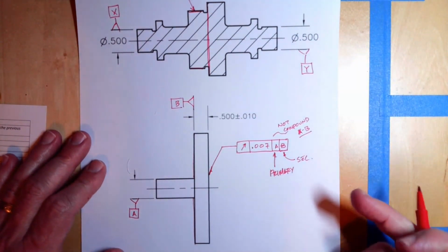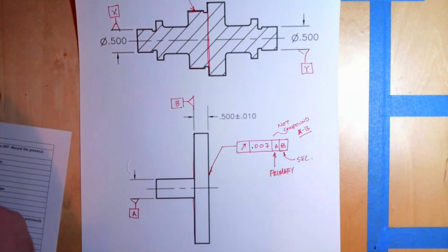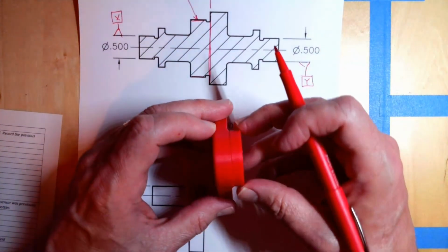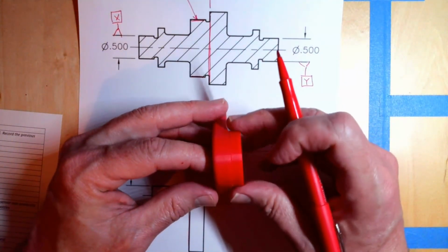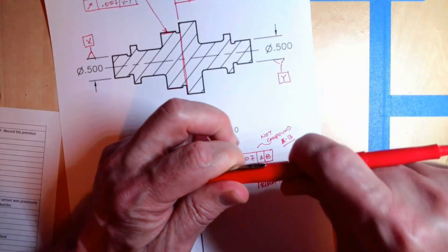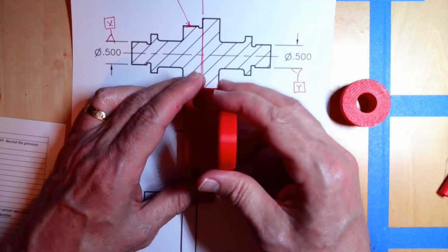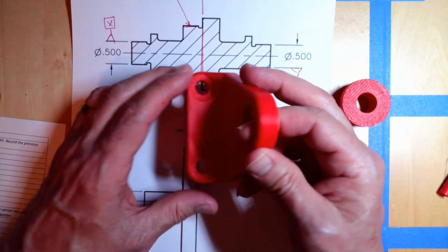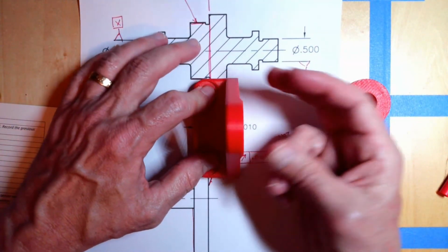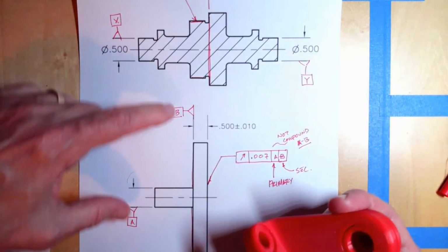Right. So with runout, we can have up to two datums. You can imagine that we can't have three datums because the part still needs to rotate. In all of these examples, the part really needs to rotate. All right. So this is one of those cases where we can't constrain the degrees of freedom 100%. Like we can, for example, with this, right? So this part right here, it's not moving when it's functioning, all right? So it's going to be held by the bolts or whatever's down here. But this part, it's designed to rotate. So we need to let it rotate through our datums.